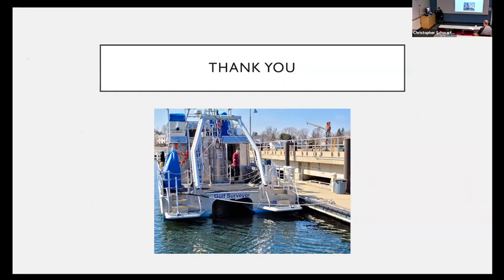So to start, the difference between crowdsourced bathymetry and trusted community bathymetry is that crowdsourced bathymetry is just simply volunteer geographic information, and that we are just logging the single beam depth values provided by whatever sounder is installed on a volunteer vessel. That data has often no metadata associated with it, and is problematic for the reasons that I had discussed at the start of the presentation.